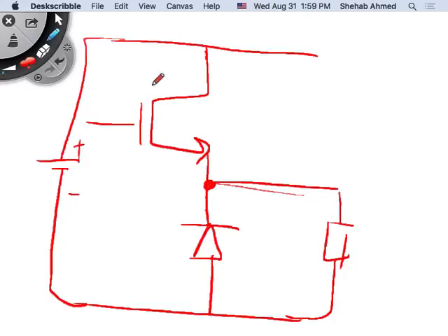How about if I turn off this device? If I turn off this device, if this current is inductive, remember, inductive current does not change abruptly, right? If you have an inductor here, remember in 214 you talked about IL of 0, initial conditions, and then this will dissipate with time if I have a resistor in the circuit, some lossy element.